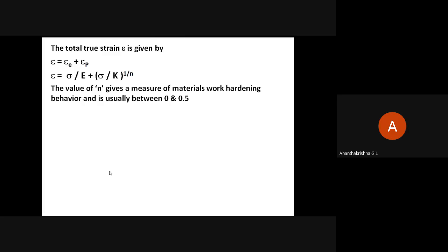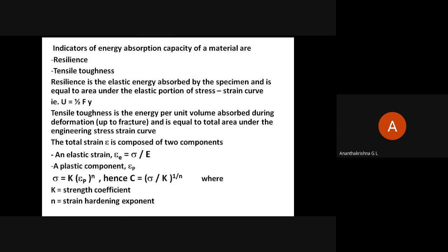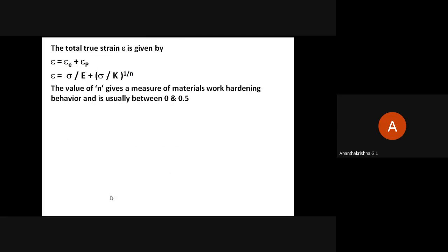So now take out your notebook and note down: the elastic strain is equal to sigma by Young's modulus, and the plastic component is given by sigma by k whole to the power 1 by n. Note down this equation in your notebook. Note down both the equations.